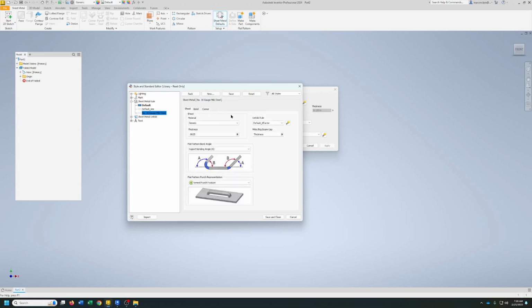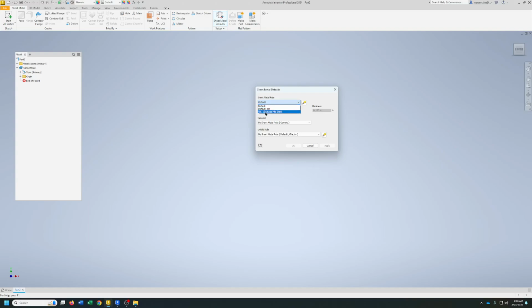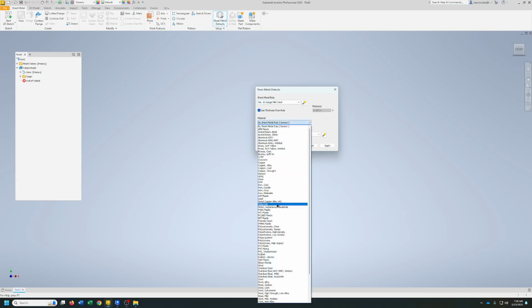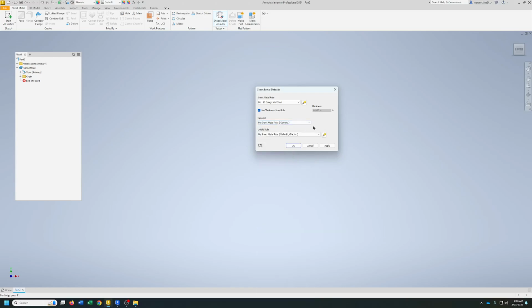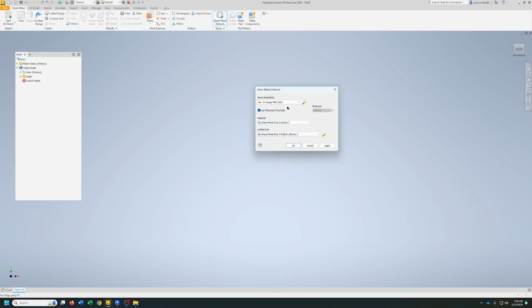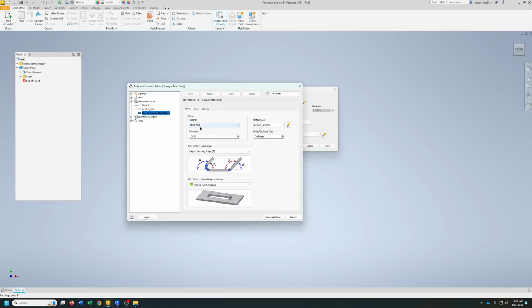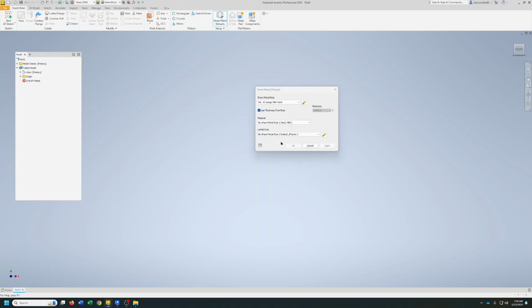We're good. All right. Now our default K factor is right here. It's going to ask us to save edits. We'll say yes. Then you're 0.44, so we're good. So we'll save and close. Okay. Change this to the number 16 gauge mild steel by sheet metal rule. That's our sheet metal rule, right? So everything is set under that. So we'll hit apply. Oop, forgot the material. Let's change that to steel mild. Here we go. Now we're good.